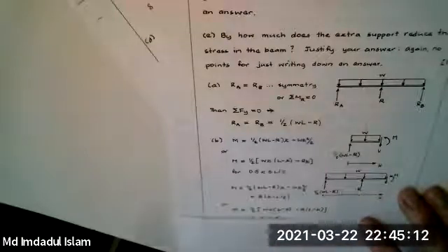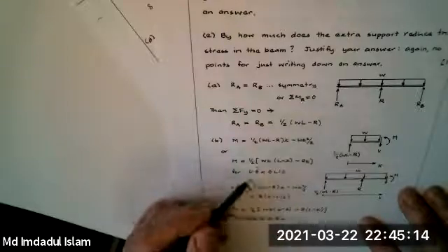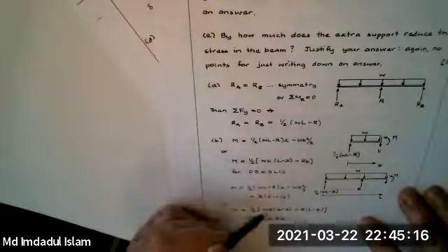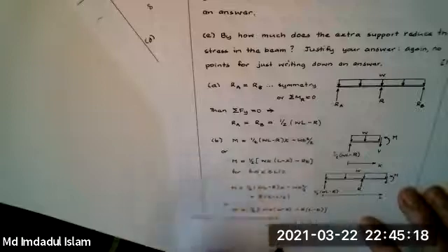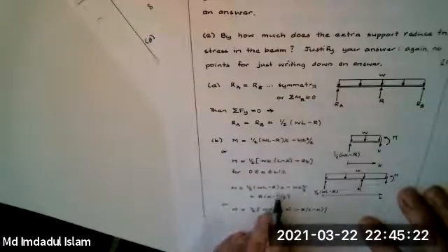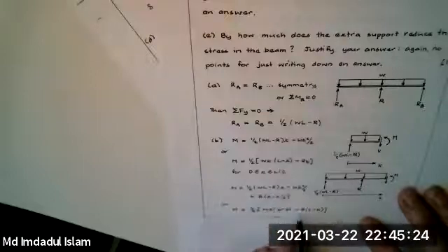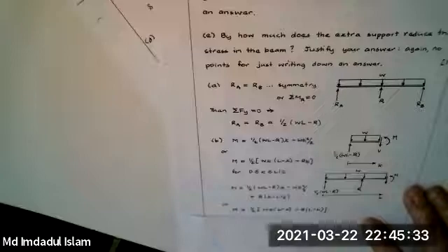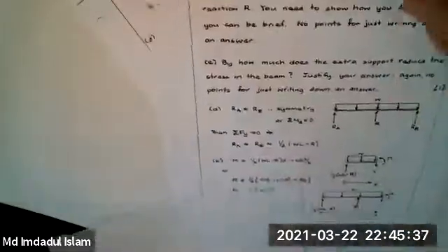And if you simplify this, the only thing that's changed is R. This part stays the same. That's actually from a beam without R. And then there's a plus Rx here, minus a half Rx here. So it's plus a half Rx, minus RL upon 2, which is what you would have got if you come from the other end. So that's critical. You're going to solve problems in engineering, and you need to be able to do these.